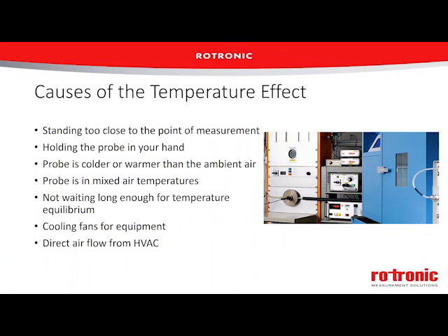We need to make sure that if we've got the probe coming from one room to another or being put into a chamber, the probe comes to equilibrium with the environment that we're trying to measure. This is very common for technicians if they're going site to site. Let's say the probe is in the car in the winter and it cools down. We need to give it enough time to warm up when we go into our environment to make sure we're measuring at the correct temperature. So not waiting long enough for temperatures to come to equilibrium can be a huge problem.